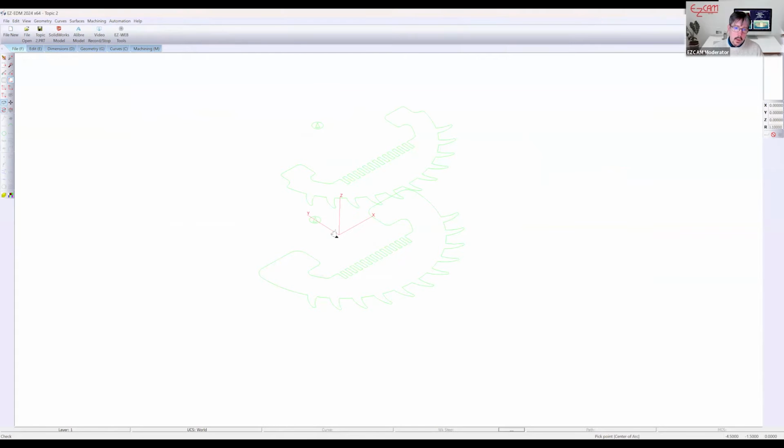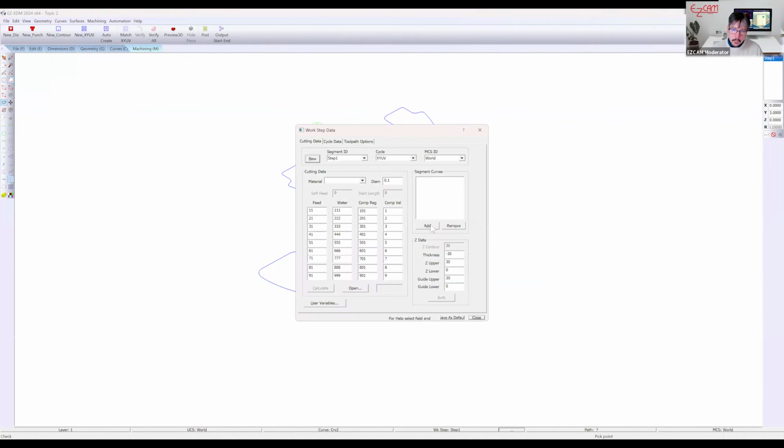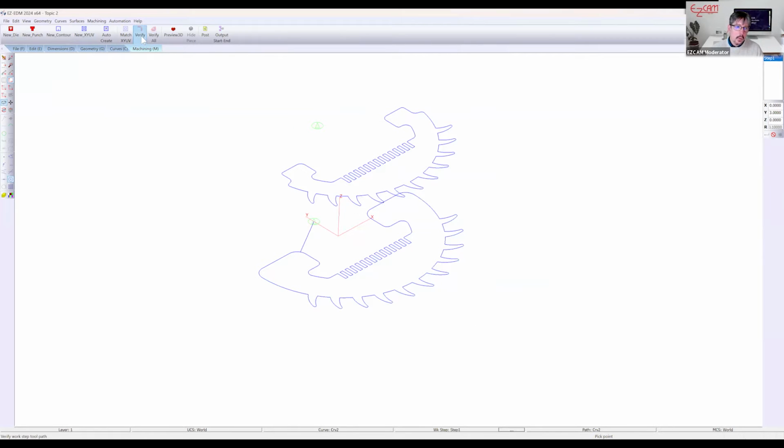And we'll look at a little bit of 4-axis using geometry. Begin with our curve. I like to start with the bottom, so that'd be curve 1. And we need our start and end. A new curve for the upper section. Now that is going to be a new XYUV. So let's add our curves, curve 1 at the bottom, top, and hit the auto button to get the distances that you need for the 2 curves.